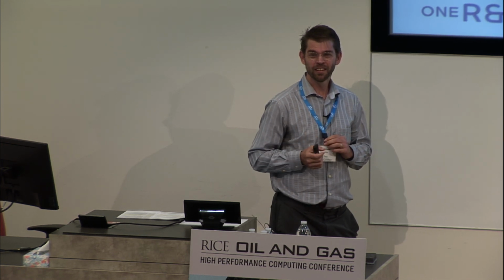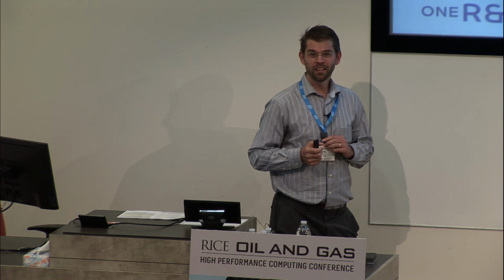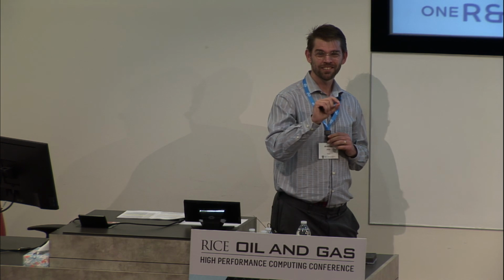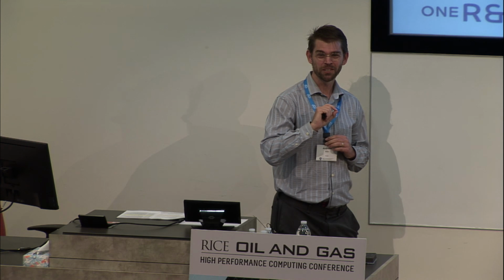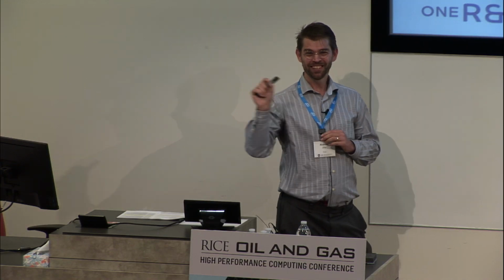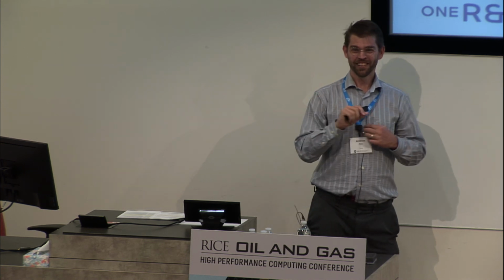So when you do this inversion, is the number of points based on...? Yeah, you have the quadrature points as your model representation. So it's represented in the quadrature points. When you compute the gradients, is it also based on the quadrature points, or on your nodal points? The gradient is based on the quadrature points, and that is why it's hard to visualize it. We just took a least square fit, and then it was a little bit artifacty at certain places.